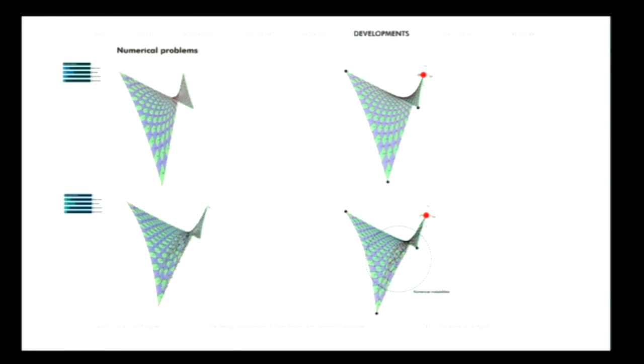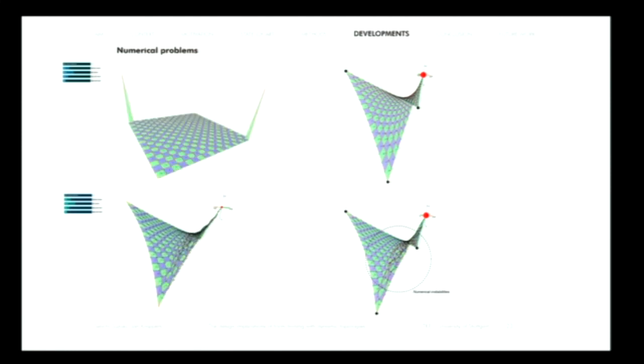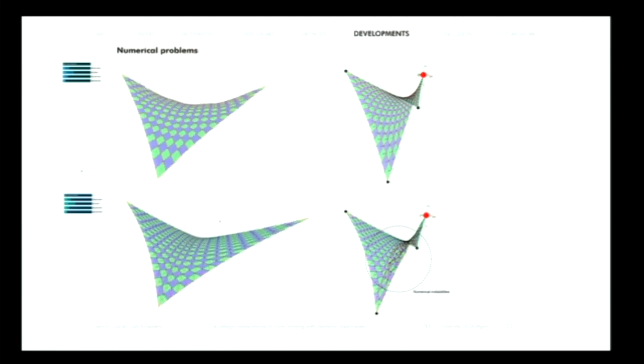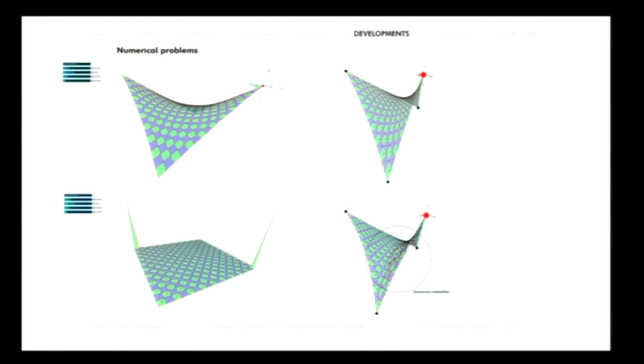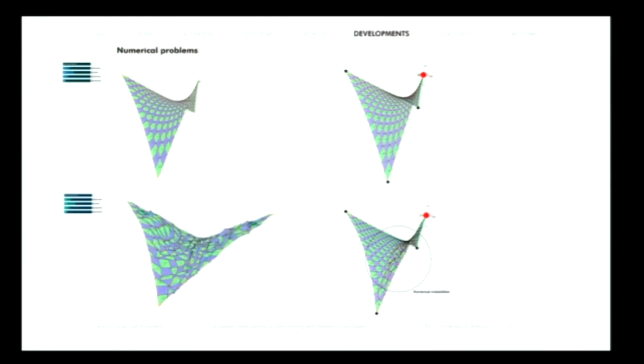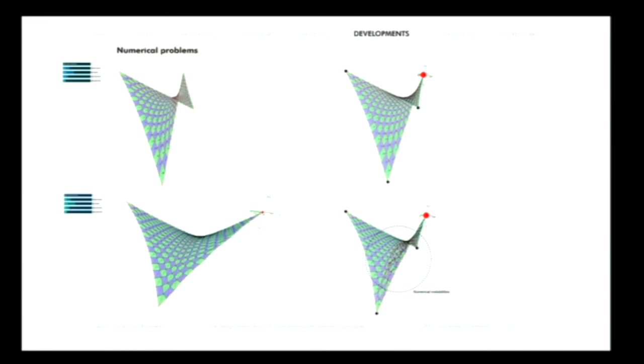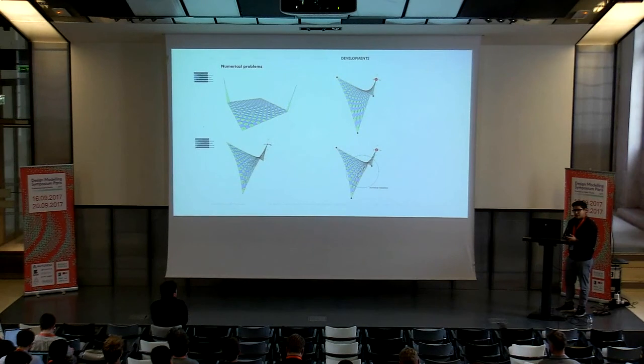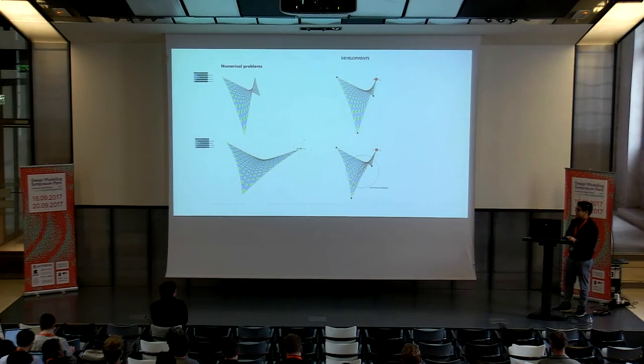The strategy is based on the construction of a hierarchy of elements that enables an interactive shift from one element to another during the form-finding process. The idea behind is that linear elements like springs and cables are among the less expensive elements to compute, but they provide a rough approximation when simulating coated membranes. To have a more accurate simulation, we need surface elements like the constant strain triangle.